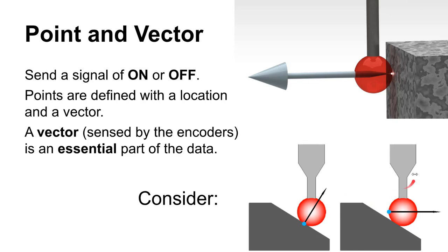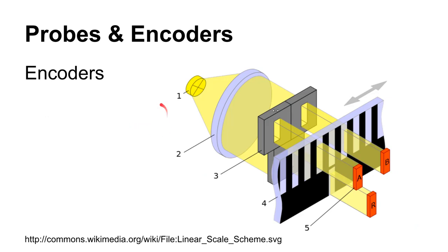Because, actually, truth be told, this surface is not perfectly aligned with the axis of travel. All right, and how do I know that? Well, because there is no perfectly aligned surface that's going to align perfectly with the axis of travel. All right, this is metrology, and metrology is a world where, if it's an actual part, there's nothing perfect about it, ever, by definition. The only perfect geometry is the mathematical geometry. All right, so let's have a look.